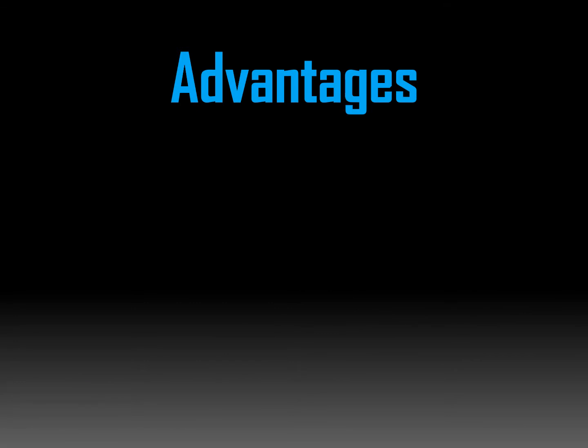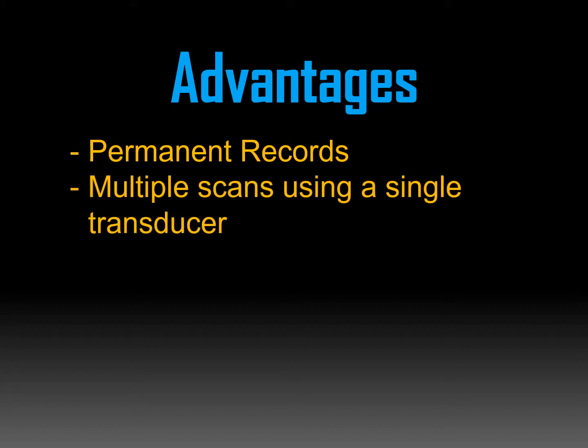The advantages of phased array ultrasonics are as follows. Permanent record. All scans and results are saved digitally and are able to be viewed, analyzed, and stored for future reference. Using a known datum point, you can determine accurate locations of defects. Multiple scans using a single transducer. The ability to take multiple scans with a single transducer means scanning speeds are essentially sped up. There is less equipment required to conduct inspections, effectively creating a relatively simple data acquisition process.